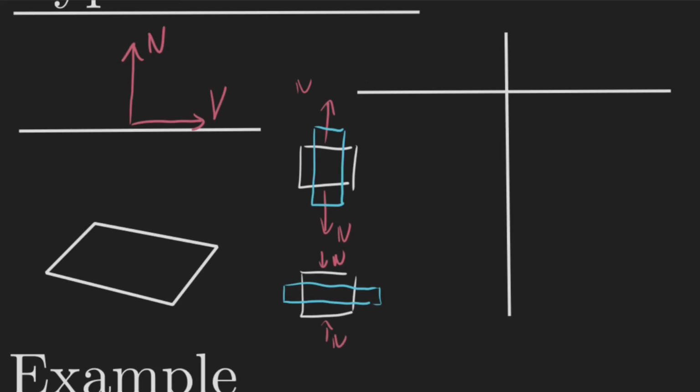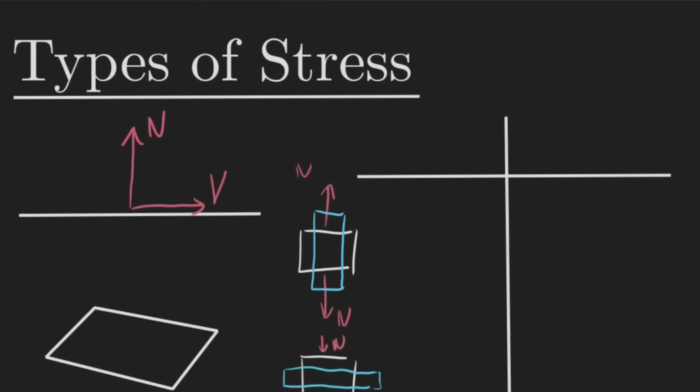Now the shear, what it looks like is basically it kind of wants to squish it into a parallelogram. So basically, if this is my original square, I'm kind of running out of room here. Why don't we go to the side? So if I have my square right here, and I do a shear force that's going to be parallel to my surface, then what it wants to do is basically shift the top portion of it to the right like this. So this is actually like, if you've taken linear algebra before, you might recognize the shear transformation, and this is where it comes from.